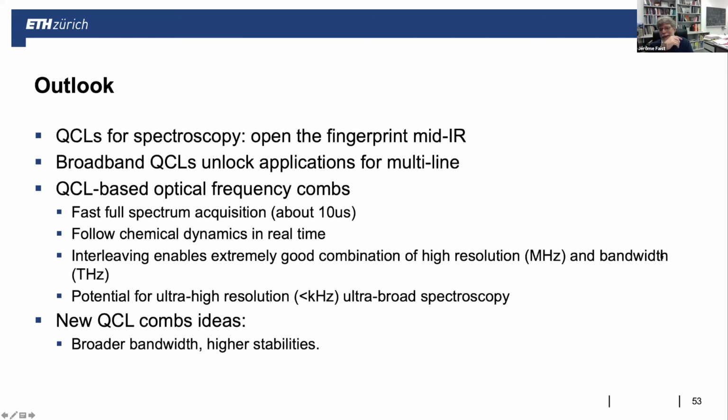If I may add, thanks for tuning in, Constantin. What you have to realize is that when you do spectroscopy with a distributed feedback laser, you do a ramp in current, and you assign a frequency to each current, and that works well. You need to calibrate it once, and then you usually assume it. It's not an absolute frequency, but it's given by the tuning of the device. Since the device is very stable, it provides a good frequency axis.